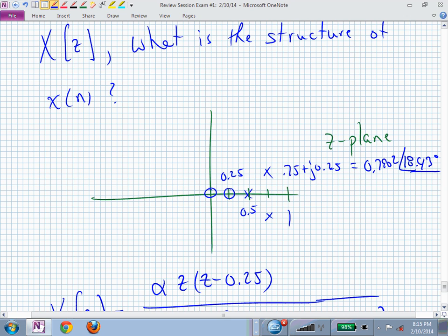So I would have had to tell you where the region of convergence really was. Let's agree that if nothing is told, or you could, on the exam, say, I'm assuming a causal waveform. And then you can say n greater than or equal to 0.